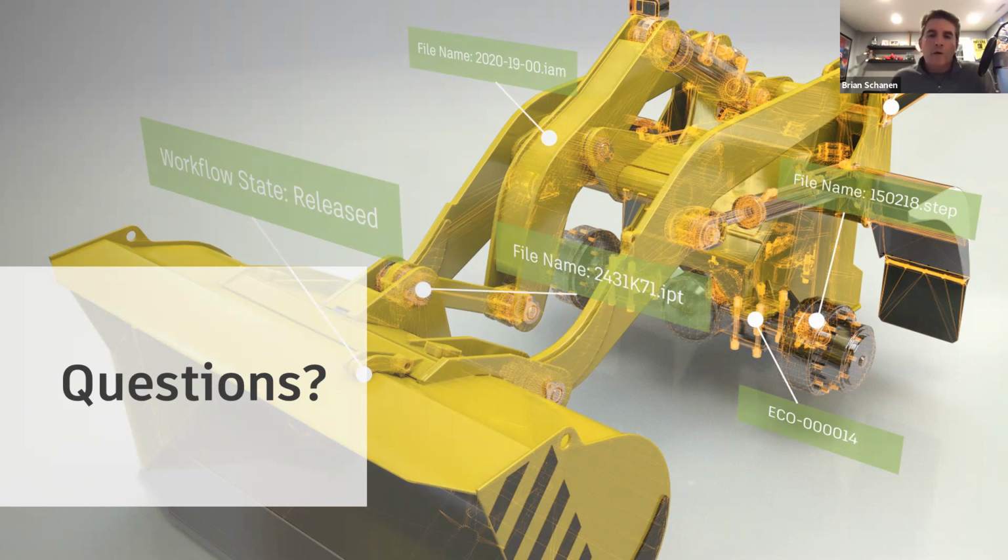But if you allow PLM to see the metadata from Vault, that can be a field, it can be a dropdown, it could be something where you can build rules inside of Fusion Lifecycle or PLM about what those different things mean. And so we enter into the customization and fine tuning of it. But yes, you can map data up into Fusion Lifecycle that is living inside of Vault.